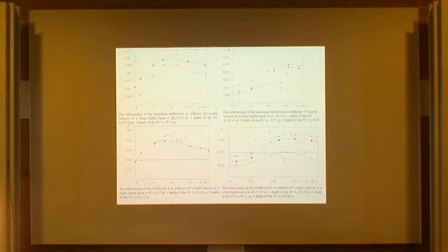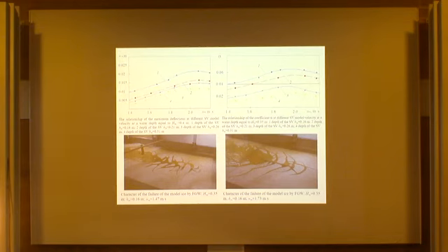The experimental study of the influence of water depth on the ice-breaking capacity of flexural gravity waves caused by the motion of a submarine vessel's model near the ice. The results of the studies show that water depth has a significant impact on the parameters of flexural gravity waves generated by the vessel's motion. Given that the destruction of the ice takes place at a velocity much lower than in deep water, the value of critical velocity also depends on the water depth.